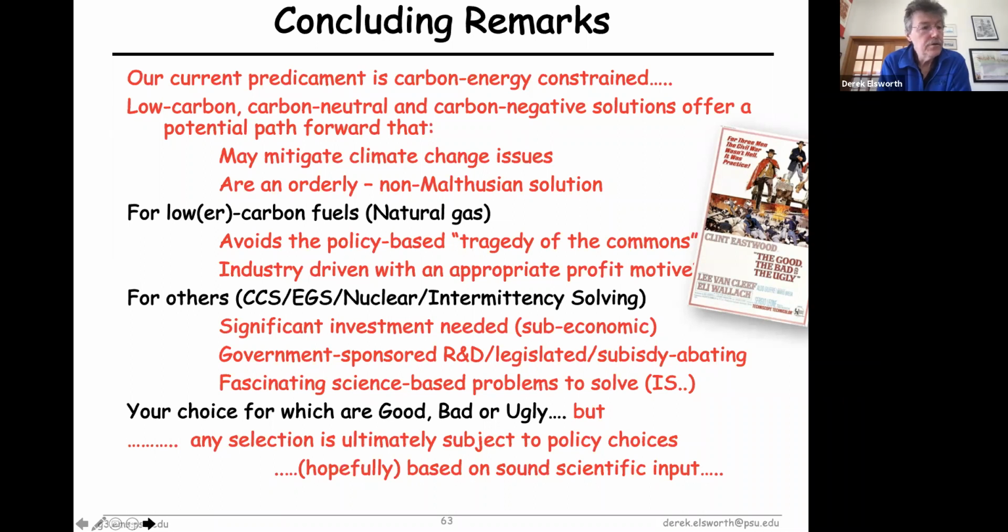And the new revolution in terms of the shale gas revolution, in terms of drilling horizontal wells and stimulating the reservoir to bring its permeability up from zero permeability essentially to some manageable permeability to recover the gas, is really not very different from the technology that you have to apply in the subsurface to be able to develop enhanced geothermal systems, to be able to create heat surface area in the subsurface and to have a heat transfer fluid that you circulate through it effectively without using up all your power pumping it, and being able to recover heat easily enough and at high enough temperature to be able to use it in some reasonable way to either generate electricity or to use it as direct use by heating, by district heating uses.